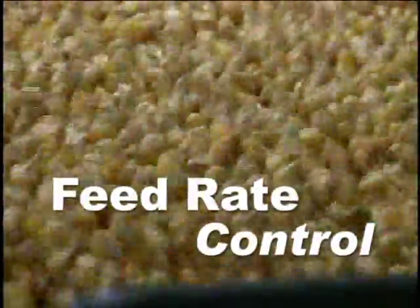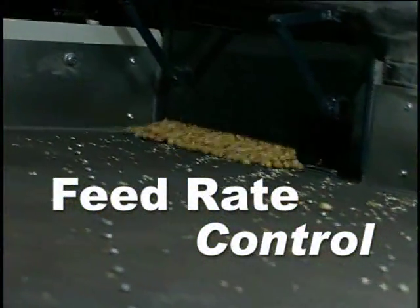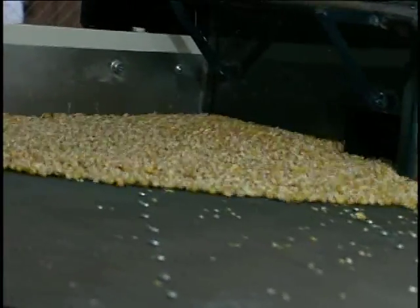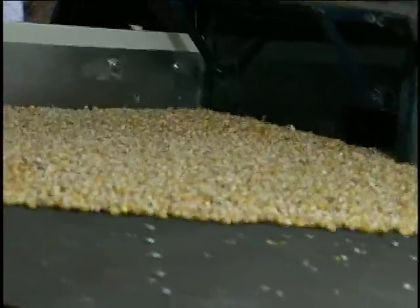Note that the product feed hopper and flow control gate move with the deck. Product flows out onto the deck of the Pegasus rather than splashing onto it from above. This allows stratification to occur immediately without disruption.